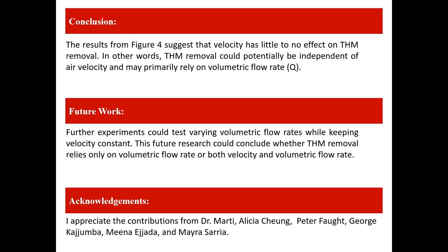In other words, THM removal could potentially be independent of air velocity and may primarily rely on volumetric flow rate. Future work could be done on this topic. For example, if a test was done on varying volumetric flow rates while keeping the velocity constant, results could conclude whether THM removal relies only on volumetric flow rate or both velocity and volumetric flow rate.